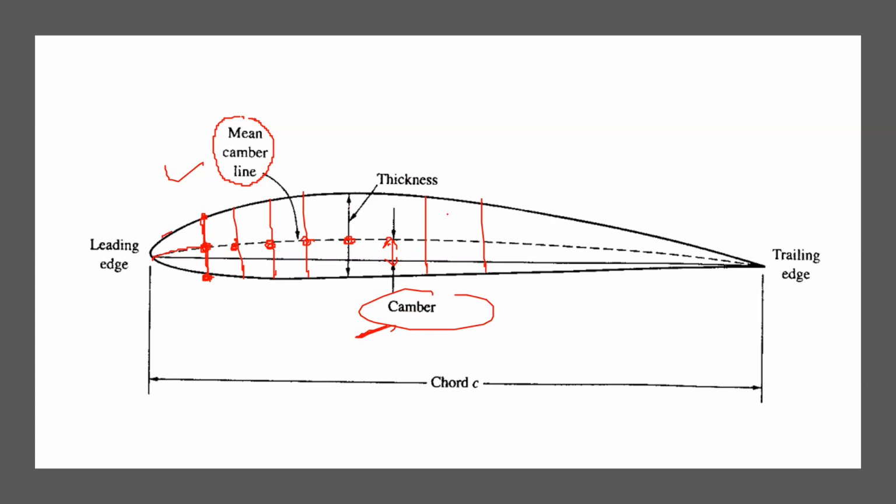Now, is it positively cambered or negatively cambered? Positively. When do we say it's positively cambered? All right. Usually we call this axis the positive axis, and that the negative axis. This distance is positive from this chord, so you call it positively cambered. With positive camber in an airfoil, alpha stall decreases. Any one of you has an explanation for that?